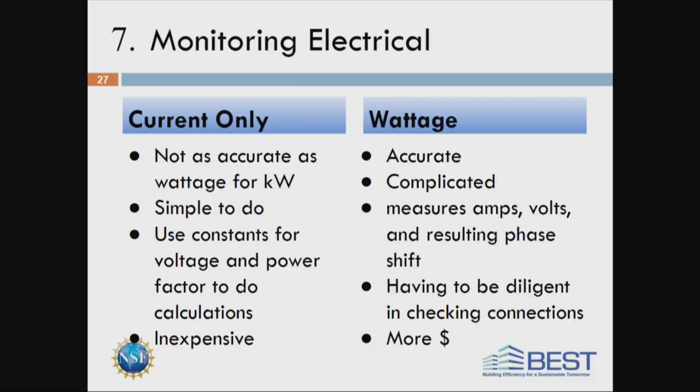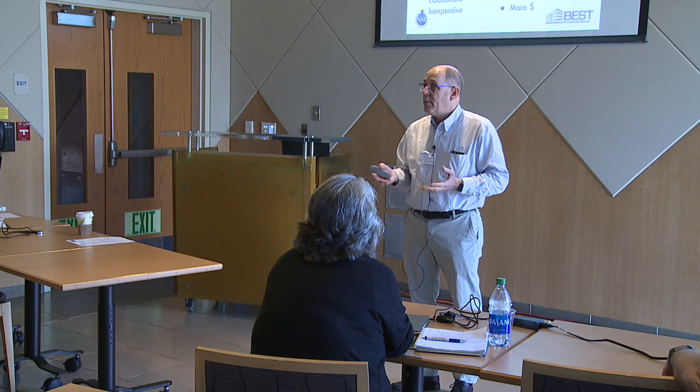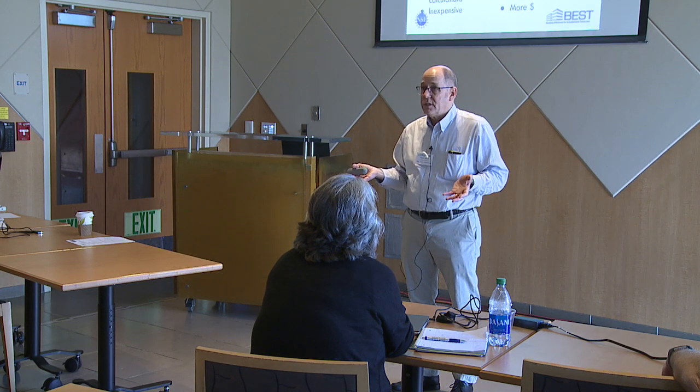So when I did my project, I was using 9 Dent Elite Pro data loggers to monitor kW, kWh, kVAR, power factor, things like that. Plus I had probably 80 to 90 different current transformers. I did this over 4 years. After one season, I told my client, it's not worth the extra money to set up these Elite Pros on all this equipment every year. I suggest we just go with the CTs and get amperage only.